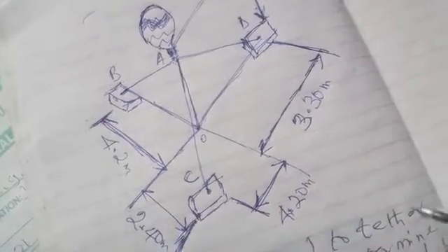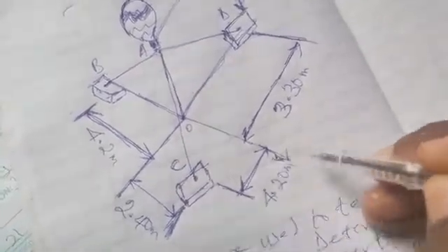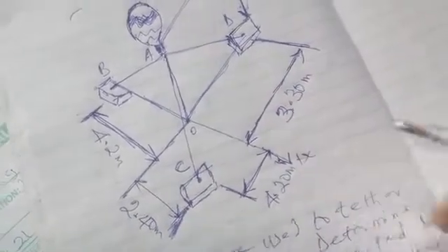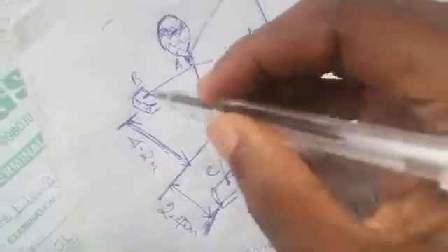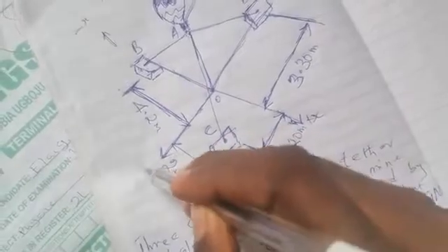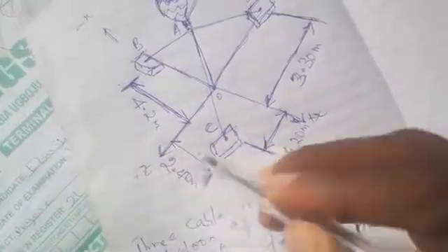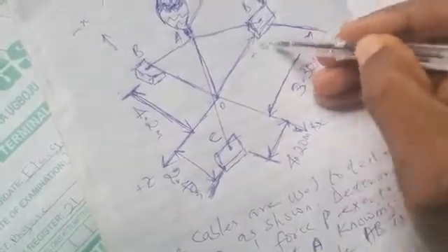In order to plot the free body diagram, we are going to label this side to be our X. So this is positive X, meaning a component pointing in this direction is positive X, and a component pointing backwards is going to be negative X. These are positive Z, this is the Z component, so if it points backwards, it's going to be negative. So these are negative Z.